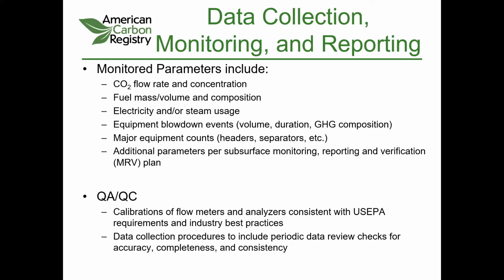If there's any equipment maintenance that is happening, or having to blow down that equipment, how much is being blown down, how often does it happen, and what's the composition of that gas, and just what's the equipment that's included within that project boundary. And then there's going to be monitoring parameters around the source, and there's going to be additional monitoring parameters, of course, around the subsurface once the CO2 is injected, and that's going to be addressed in the MRV plan.